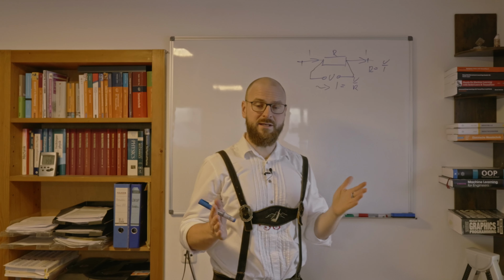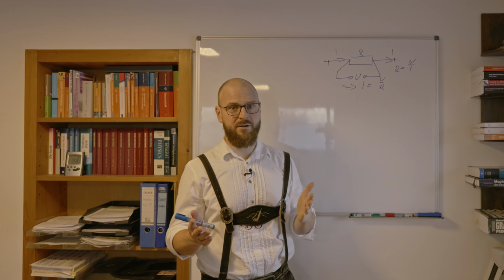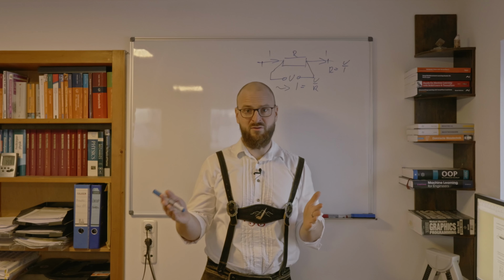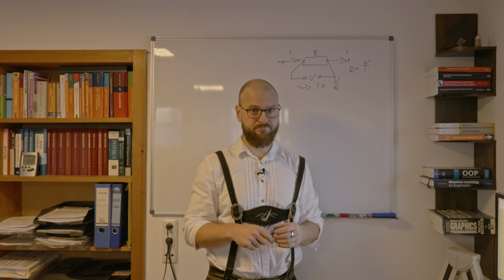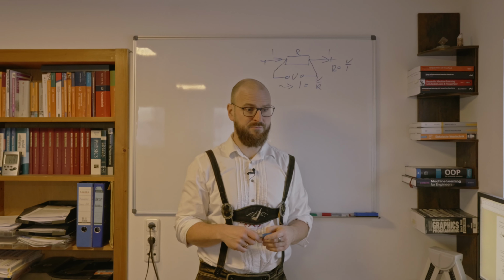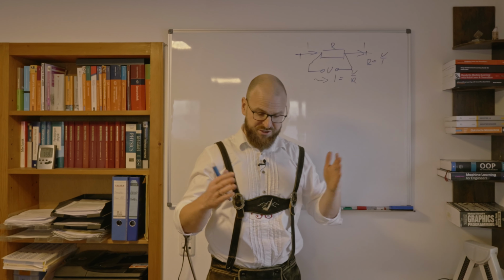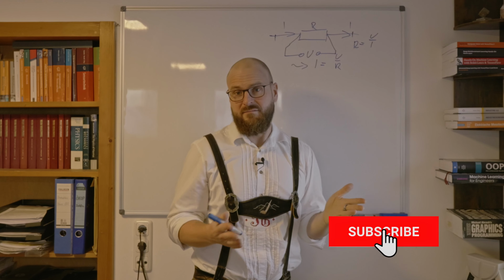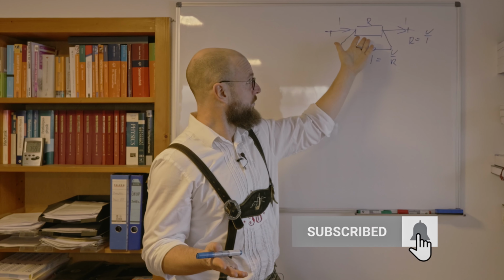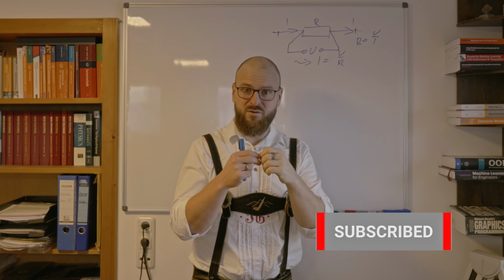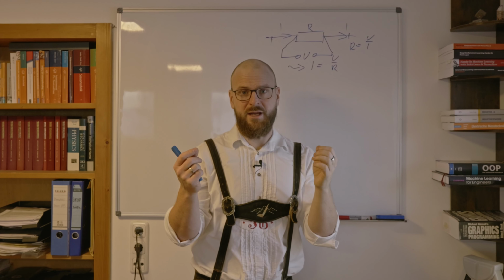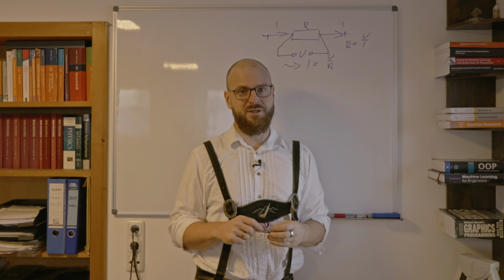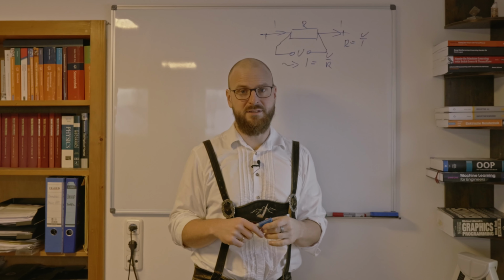So imagine you're in industry, you want to measure the current a machine uses. Why would you measure that current? Well, you know the voltage, you measure the current, you get the power that machine consumes. And that machine already runs and you want to add that current measurement. That gets you to the problem when you want to use an ohmic resistor, because you have to open the circuit the machine is connected to, insert that resistor, and then drive the machine again. So you change the electrical system.